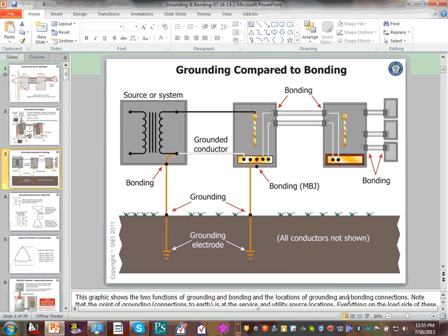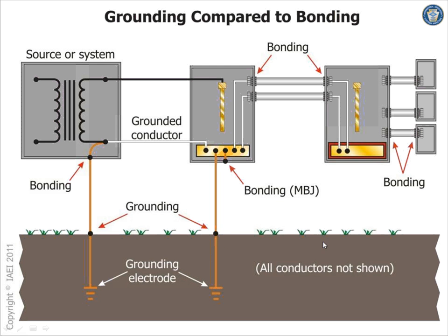Now that we know at least what the system can be grounded and not, we have to decide if we want to ground a system or not, based on the application of that system. I dare to say 90% of the systems that we run are solidly grounded in the 480, 277 systems. If you go higher than 480, 13.8, 4160, then they run a lot of impedance grounded or ungrounded systems. A lot of impedance grounded. Okay. Any comments, guys, corrections? You're familiar with these systems. Anybody has any inputs before we move into grounding the equipment?